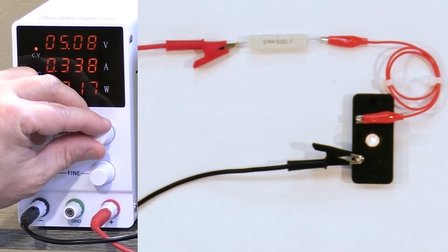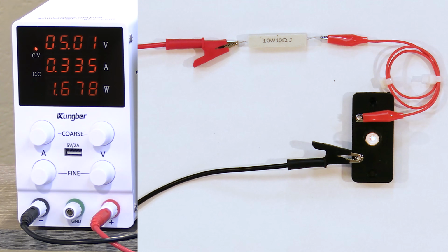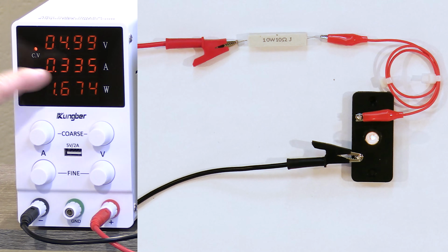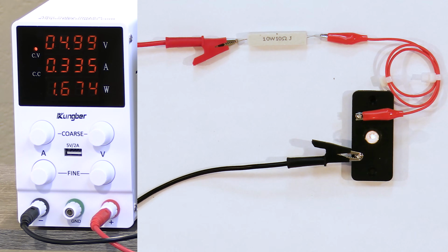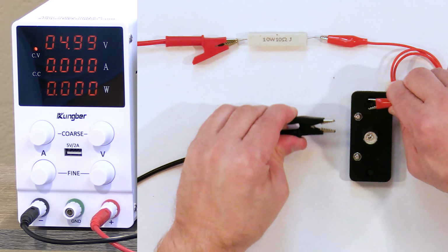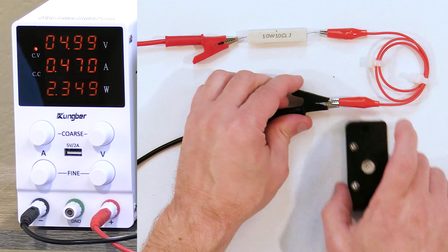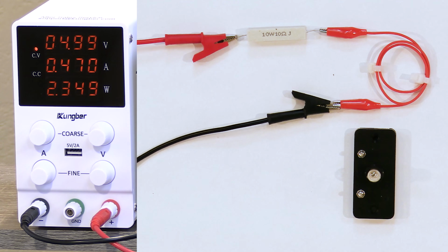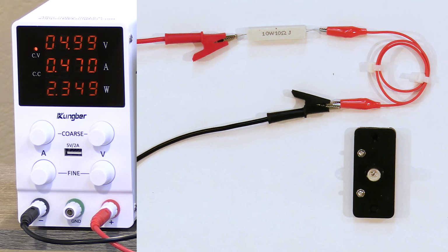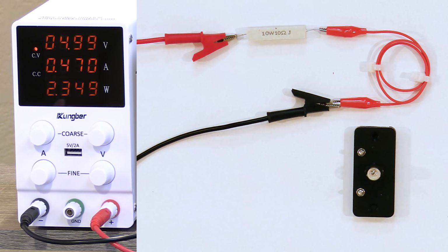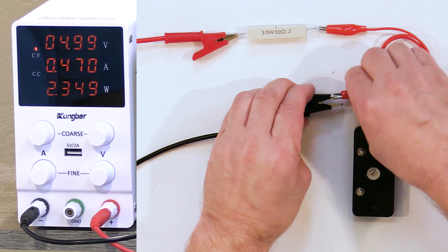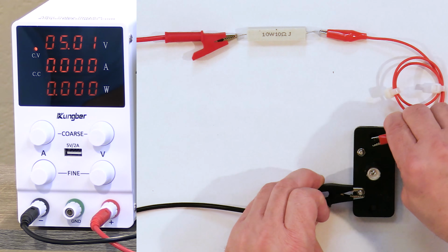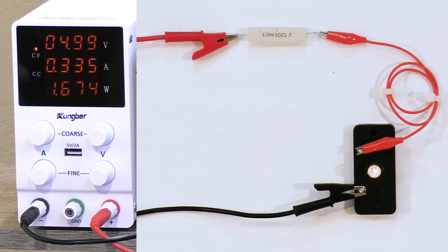But I want you to notice something: the current flowing through this circuit is 0.335 amps, right? But if I take the light bulb out, so it's no longer there, and I just have it go through the resistor by itself, this is what we had before, the current is a little bit higher, 0.470. And actually, it was a little bit higher before. I told you these things can change. This thing is actually getting kind of hot right now. But I mostly wanted you to see that there is a difference in the current when I introduce the light bulb. Why is that? Shouldn't everything be governed by Ohm's law?